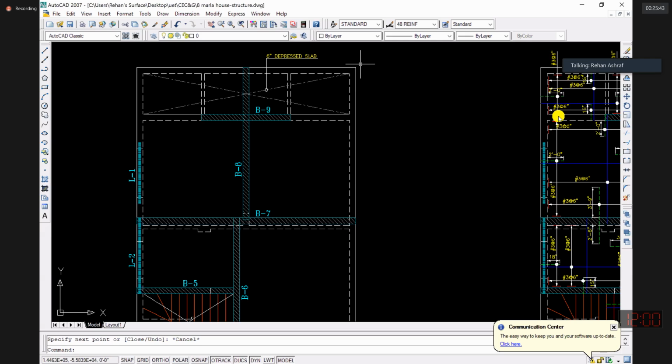Because the outer side is the periphery of the slab, so this would be a solid line, and these walls would be basically underneath the slab, so they are shown with dashed lines, right? Why are beams shown with solid line? Why is the outline of the beam shown with solid line? Because beams are coming with the slab, concrete slab. That's why they are shown with solid line.